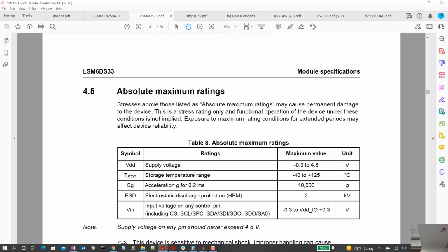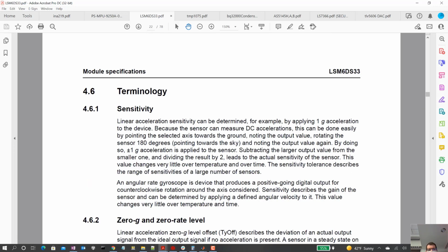That would require 7 bits. That would require, well, not 7 I/O pins. It would require only 3. Is that it? No, 3 would be only 8 different addresses, wouldn't it? So you would need 7 pins to do all of those 127 addresses. So that's kind of wasteful. Normally you don't need that.